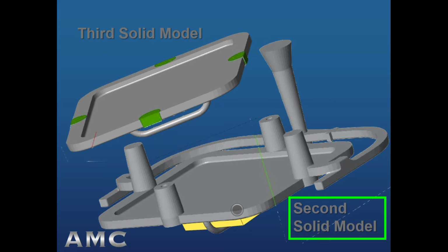And all metal casting alloys have different pattern maker's contraction rates. This is an aluminum silicon alloy, A356. Also added to the second solid model are the parting planes. There's a parting plane across here. Draft is on this surface.